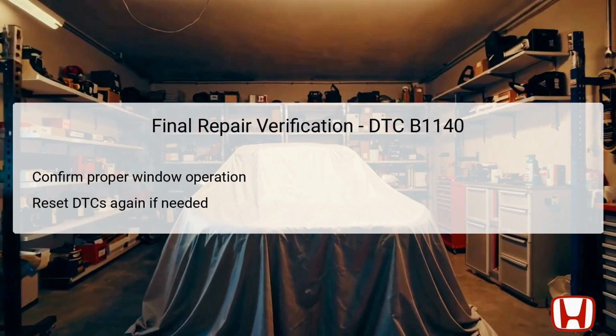In the final repair verification stage, you will want to confirm that the power window operates correctly after repairs are completed. It's paramount to check the window's functionality by operating it several times to ensure everything is working as intended. If any DTCs are still present after procedures, you might need to reset them again using the HDS, reinforcing that a successful repair has taken place.